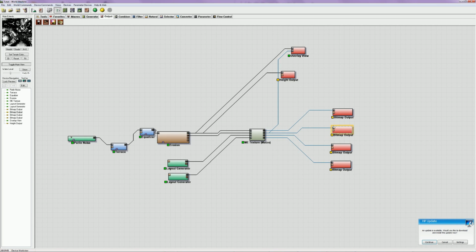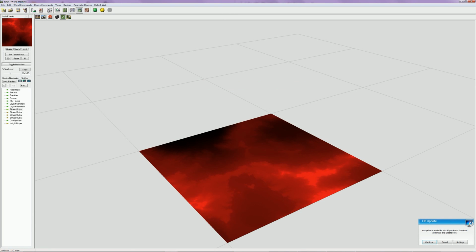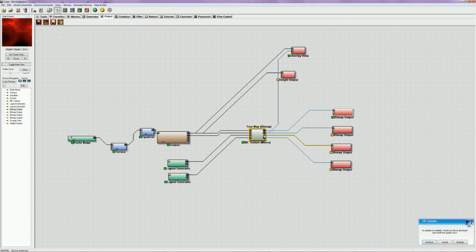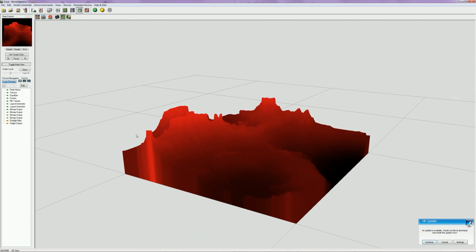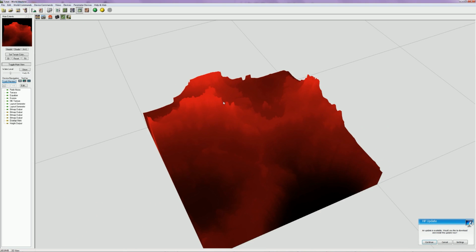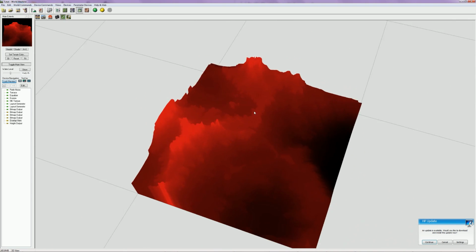So yeah, look at each of these to make sure they look right. I'll explain a little bit of what they are. Build. Oh wait, no. To get this to here. And, a neat little trick is to press F, and that means preview is locked. So if you click somewhere else and change properties, it'll still stay. Now this one is the height map. Values get higher as the height increases.